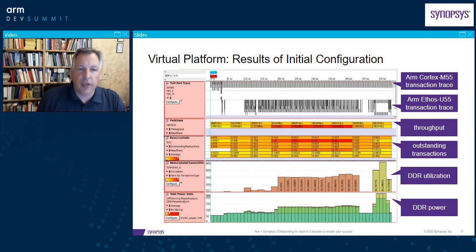So let's go to the next slide, where we see that. This is a visualization of the result of such a simulation. As a result of a Platform Architect simulation, you get an analysis database with performance measurements, or traces, that you can slice and dice to help you analyze the performance bottlenecks, functional issues, or display the key performance indicators of your hardware.